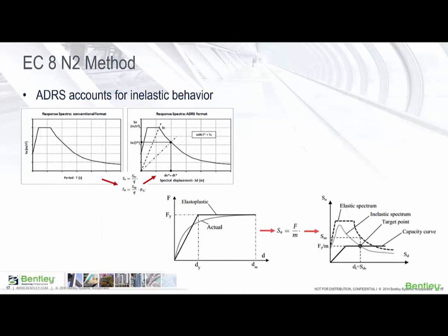Eurocode 8 N2 method. Finally, in the Eurocode 8 N2 method, the response spectrum in the conventional format of spectral acceleration versus period is converted into ADRS format. This conversion accounts for the inelastic behavior through the use of empirical ductility factors.